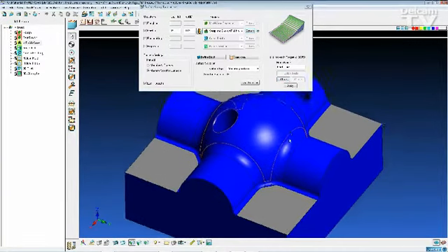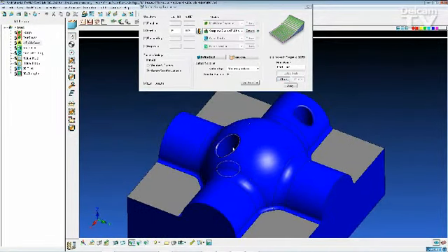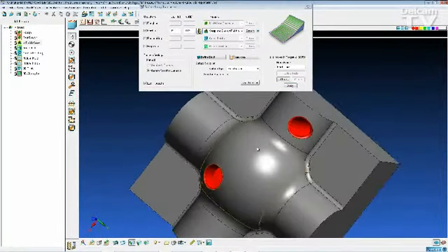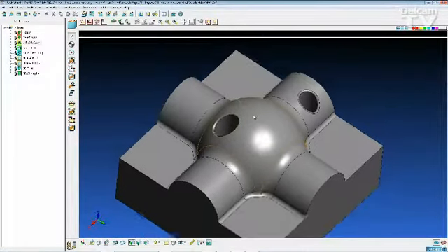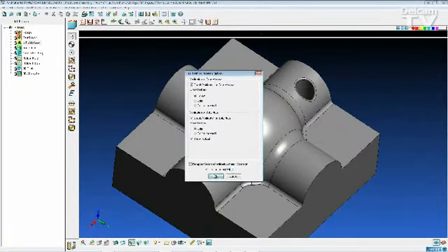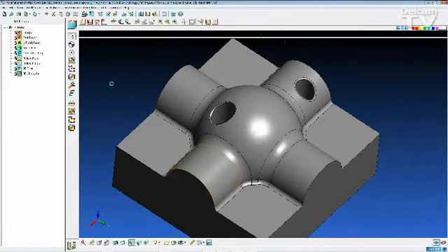Now, something with this toolpath that I've set up is hole surfaces. So with hole surfaces, you can see I've got the holes selected, and PartMaker will automatically patch these holes as if they're not there without having to change the model.